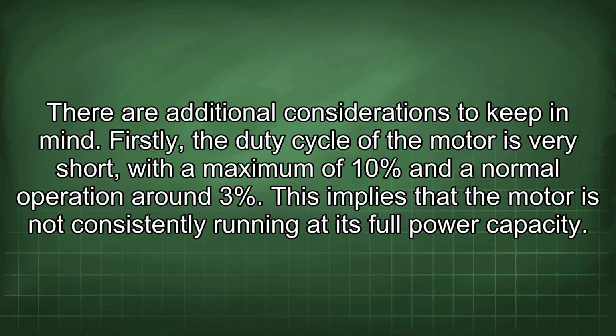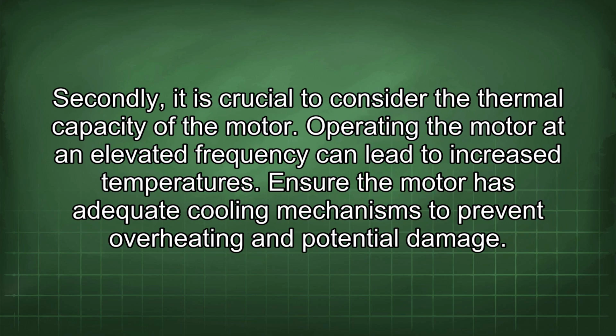There are additional considerations to keep in mind. Firstly, the duty cycle of the motor is very short, with a maximum of 10% and a normal operation around 3%. This implies that the motor is not consistently running at its full power capacity. Secondly, it is crucial to consider the thermal capacity of the motor. Operating the motor at an elevated frequency can lead to increased temperatures. Ensure the motor has adequate cooling mechanisms to prevent overheating and potential damage.